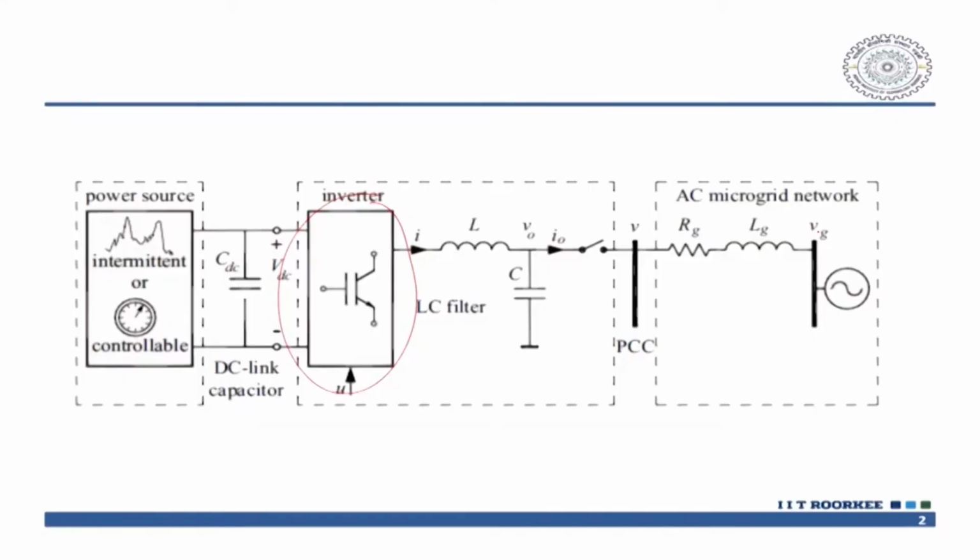You know what happened, this topology can act also as a shunt active power filter at the point of common coupling. So, the filter is required to be a little higher side for it to be actively used as an active power filter, and it can be coupled with the distributed generation like solar and other entities mainly. Then it can have the power to compensate the reactive power. Apart from the reactive power compensation, it can compensate the real power. So, this kind of integrated topology is gaining advancement, and this distributed generation and the power quality, both these issues have been integrated, and it looks like an integrated problem nowadays. And how it is done, let us see.